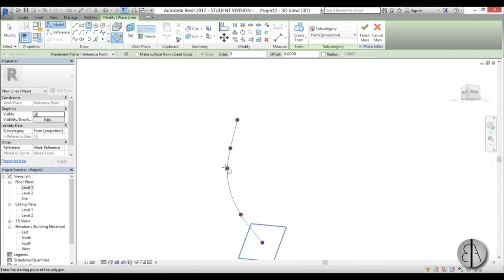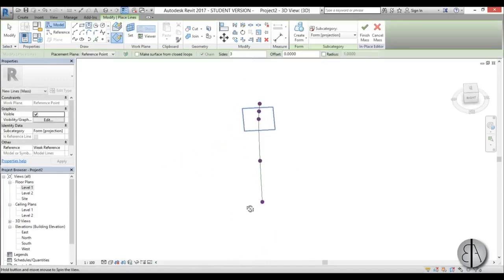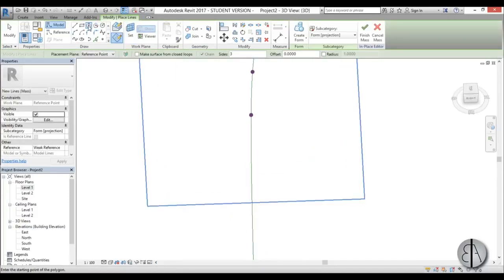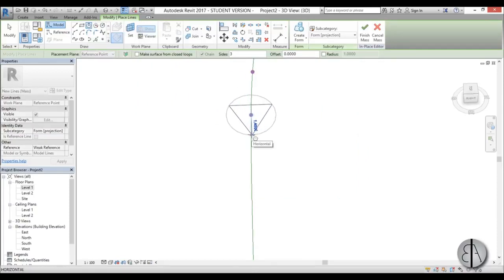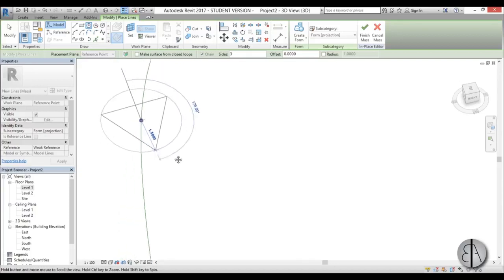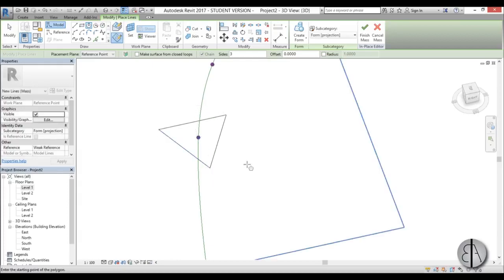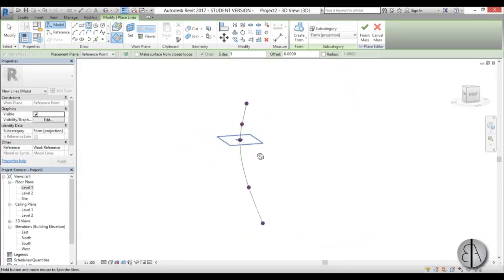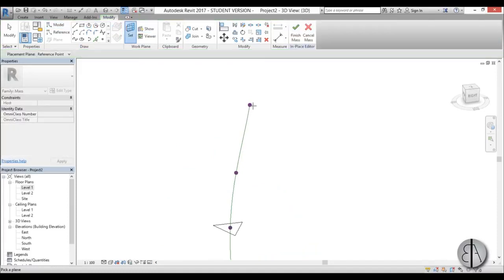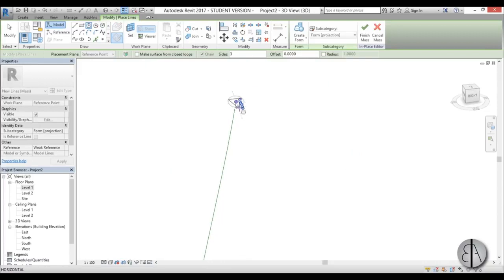And then this is the crucial one, the middle one, so I'm just going to set the work plane to that. Maybe we can go up like this. Okay, now again go Inscribed Polygon, 3-sided, choose this side, and then again you pull it out when you have this blue guideline, so it's kind of perpendicular to the structure. Yeah, like this, and I'm going to put it at 1.5 meters for that one. And for the final one at the top, just go Set Work Plane, set this one, and then just place it, and again something real small, like so.